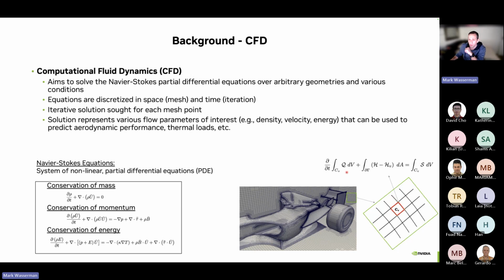By formulating the Navier-Stokes equations for this small control volume, we can break down the solution of the equations to a set of many solutions for all the discrete cells that are shown in this picture that actually include all of our domain. And as you see, for example, in the race car here, it also includes the body of the vehicle.